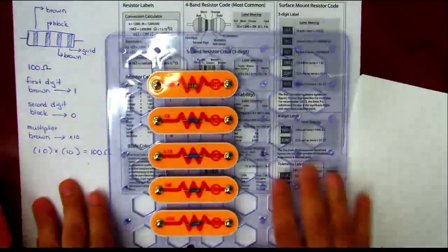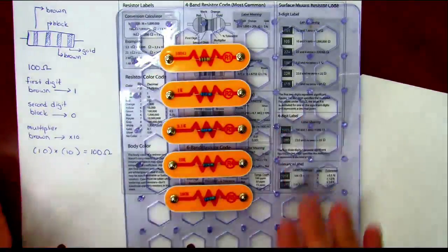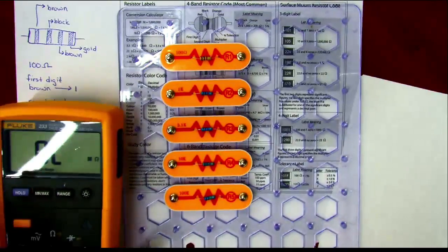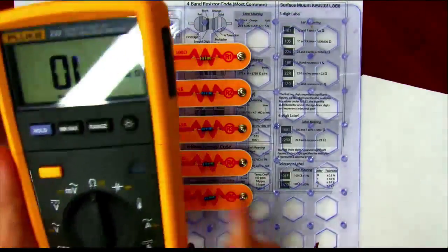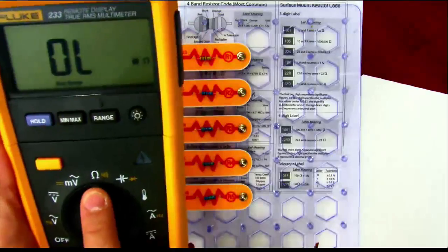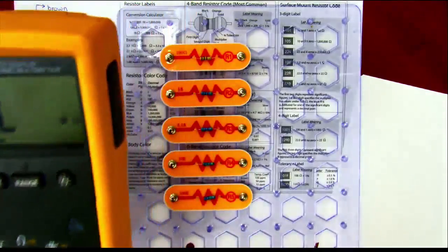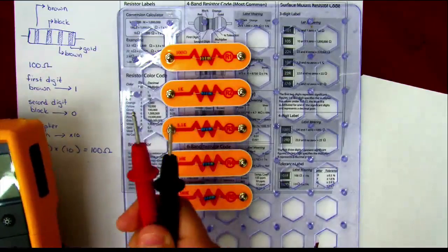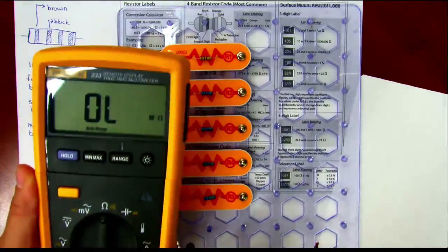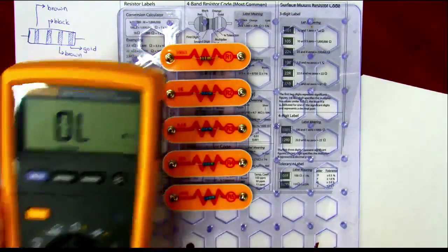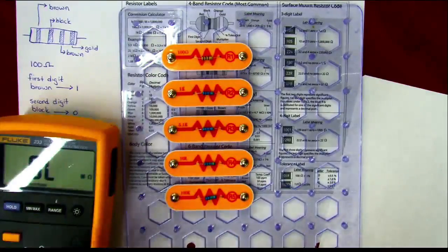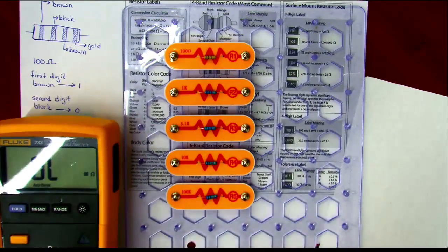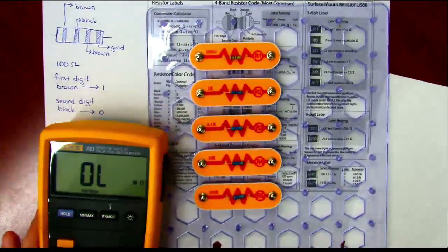Your tolerance is for the number coming across there. So for example, it's supposed to be a 100 ohm resistor, so we have our meter. I'm going to pass this meter around too. If it gets turned for some reason, it should be pointing to the ohms as you're going around. There are 2 pointy things on here. Don't poke anyone with these, the adults. So we have our meter, we have ohms on here. It's overload because I'm not touching anything.